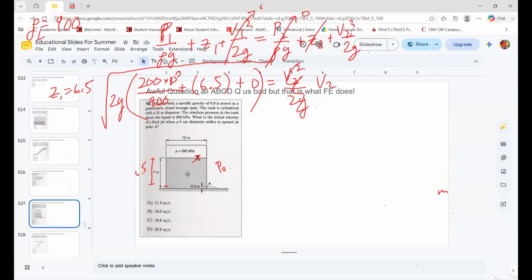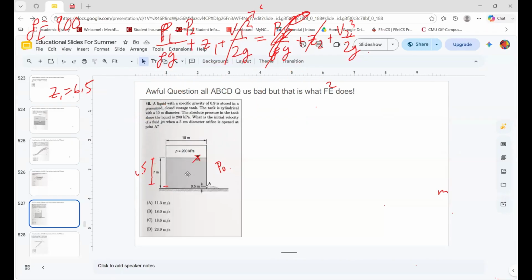So, hmm, well, technically speaking, actually thinking about it, you should do minus P. I think I was wrong. I think this one actually does matter because I'm getting insane numbers. I'm getting something stupid, so I think this is wrong. Let me just recheck it. You have to know what P2 is, what the pressure is to subtract. So that means it is actually the square root of 2g multiplied by parentheses P1 minus P2 divided by rho g.